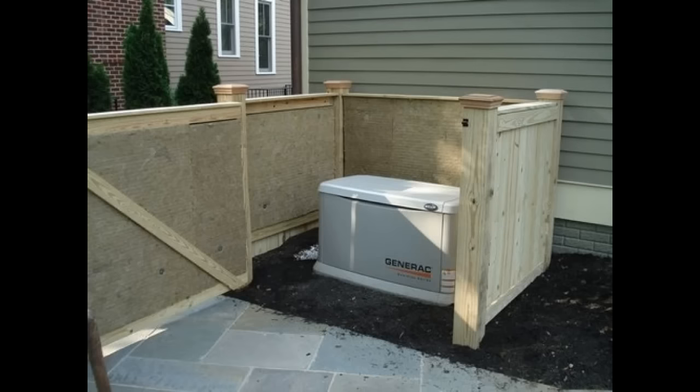Now, let's say that this is the noise source that's bothering you. You want to measure the decibel level near that noise source, and then you want to measure the noise level at the position you are where it's annoying you. It's often easiest to deal with the noise at the source, to block the noise, to absorb the noise, to reflect the noise some other direction.